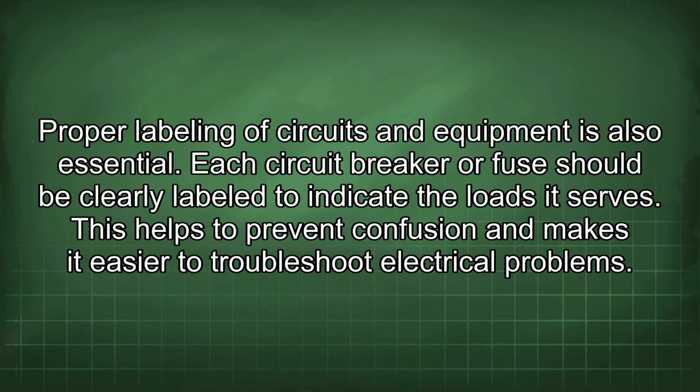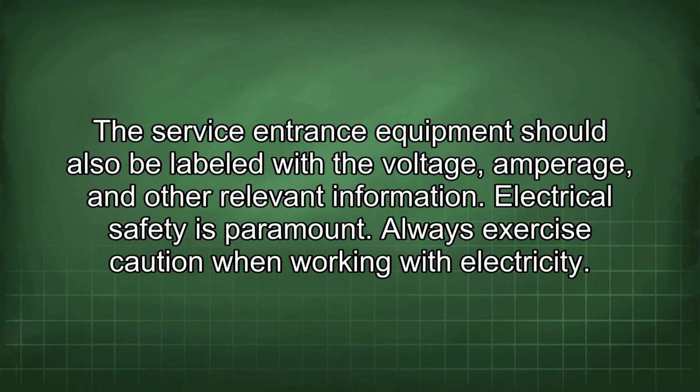Proper labeling of circuits and equipment is also essential. Each circuit breaker or fuse should be clearly labeled to indicate the loads it serves. This helps to prevent confusion and makes it easier to troubleshoot electrical problems. The service entrance equipment should also be labeled with the voltage, amperage, and other relevant information.